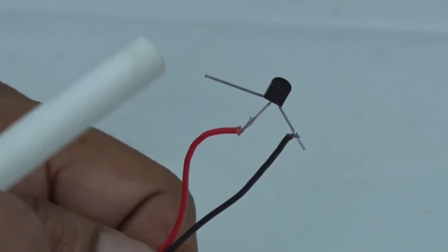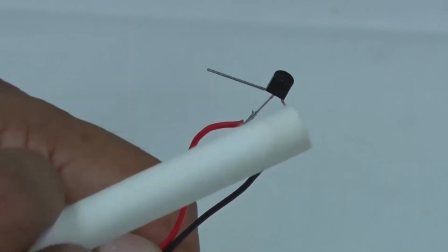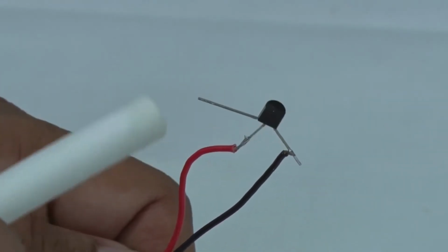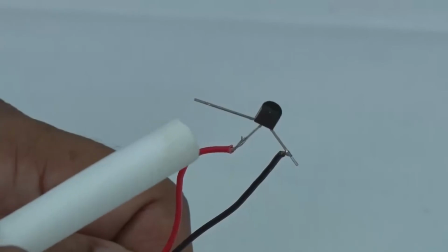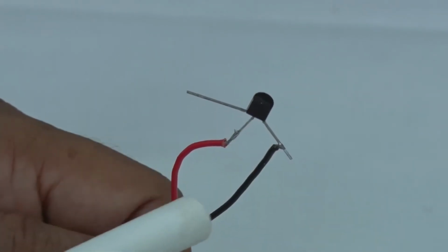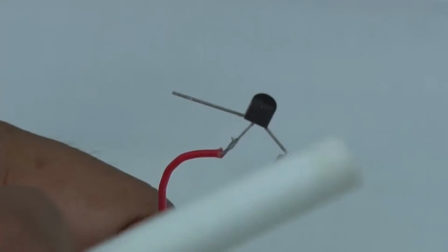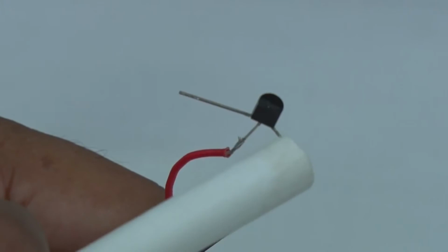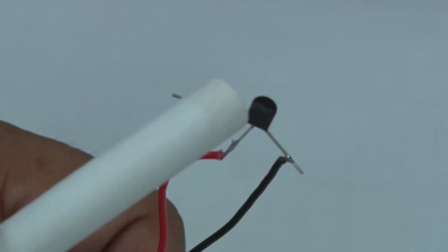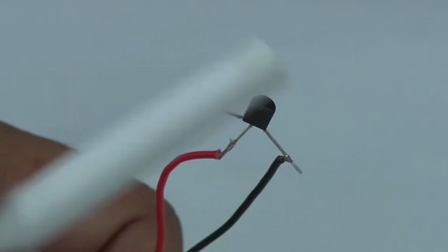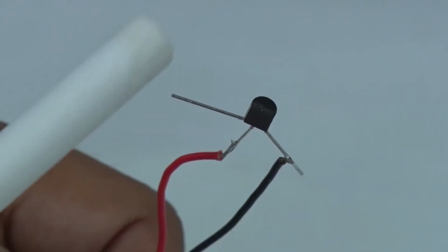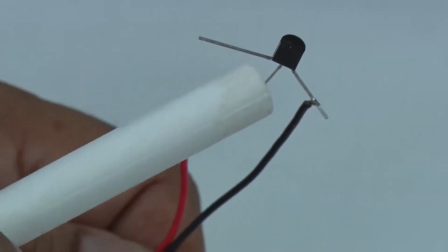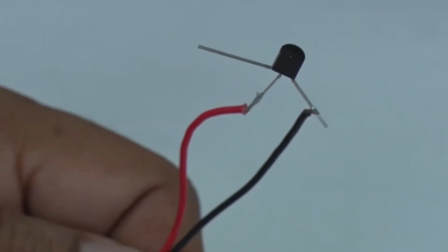This is a low power transistor, used for small currents. Then you have other kinds of transistors where the casing is metallic, a full cylindrical type of thing, and from the bottom there are 3 leads coming out. In that circular cross section on the top, there is a notch from which people find the first lead, second lead and third lead, and then the data sheet will say which is emitter, which is collector, and which is base. So this is it. I will just show a particular experiment with this transistor.